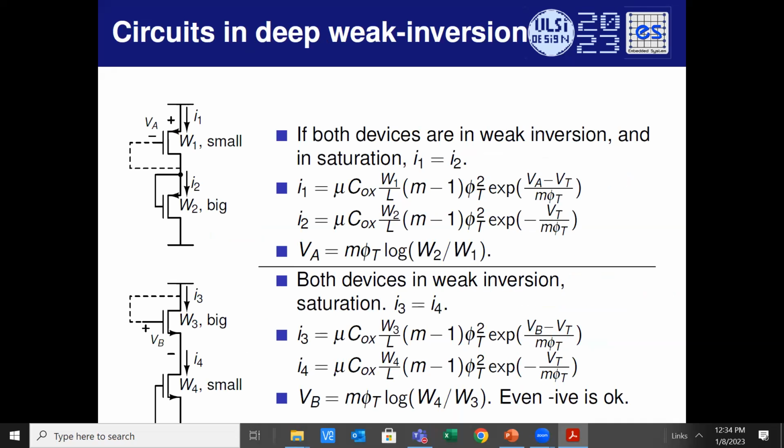Okay, that's interesting. And the band gap reference voltage is also in subthreshold, right? I mean, that's about 200 odd millivolts. So we will have a limitation. If we have to use this band gap reference voltage somewhere outside, probably we have to use a PMOS. NMOS based is not possible because designing any subthreshold circuits in the application may not be as easy. Right? Okay. Thank you.